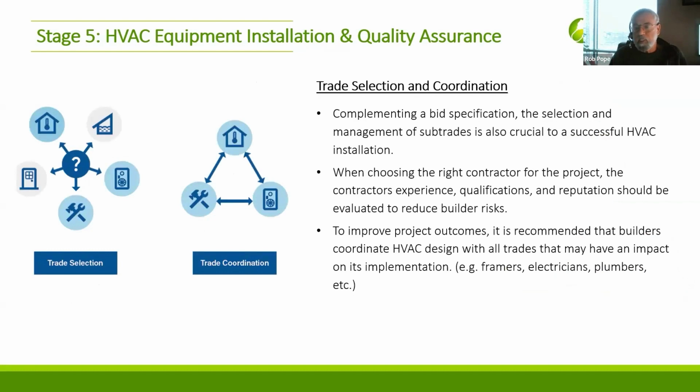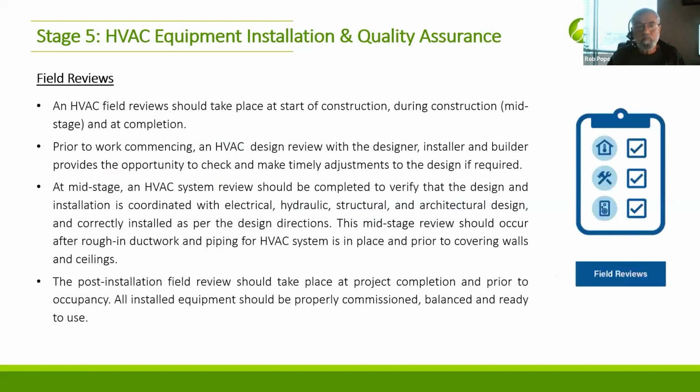It's not enough to do a design and then the HVAC contractor starts working on it. You've got to make sure everybody surrounding that HVAC contractor also knows the design. Where's the framing? You want a grill, for example, to end up under a window, right? You want the framer to know, leave that spot, start your centers from here, or adjust that spacing in the choice so that you don't get asymmetrical outcomes. The simple things like that. Making sure the plumber knows, don't run it down the center of the room, I need that for the trunk line for the HVAC. Everybody surrounding that can impact the execution of that design, so it should be coordinated.